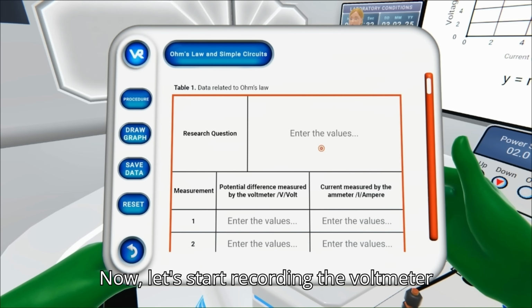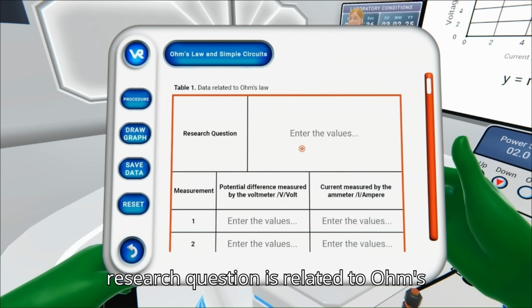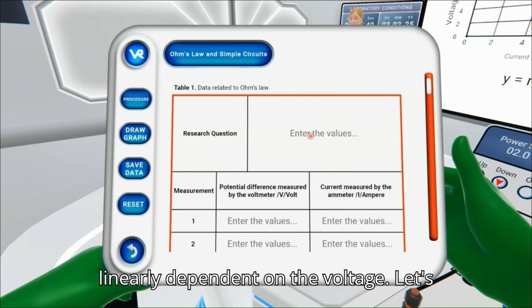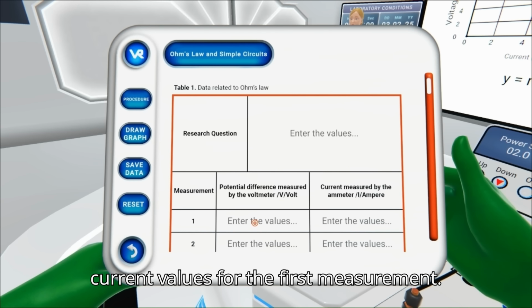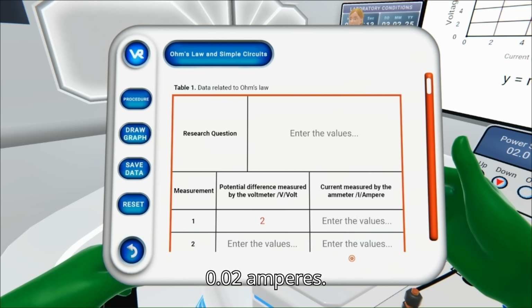Now, let's start recording the voltmeter and ammeter values in the table. The research question is related to Ohm's law, so you can expect the current to be linearly dependent on the voltage. Let's begin by writing down the voltage and current values for the first measurement. This is 2 volts, and the current is 0.02 amperes.